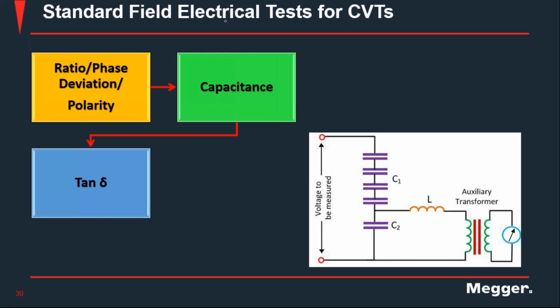The criteria to analyze these results are a little bit different than the other aspects of these measurements we do for instrument transformers. We do not have a hard limit or number that we're looking at, depending on the type of CT. This has more to do with the application of that particular instrument transformer. Where is it installed? What is the purpose of that instrument transformer? Again, there is no exact number or limit in terms of percentage that you're looking at.